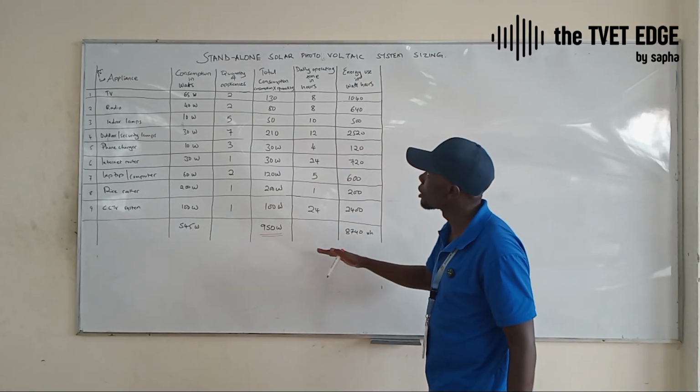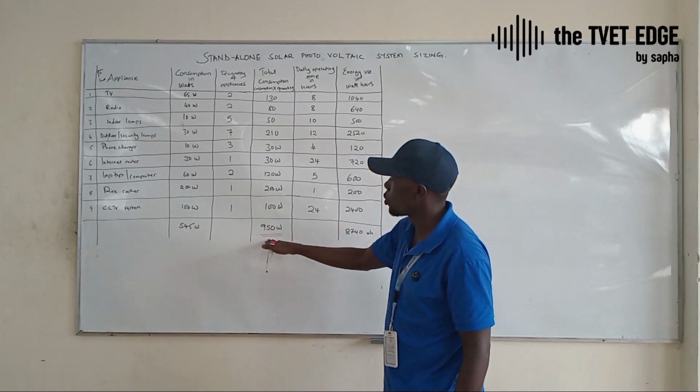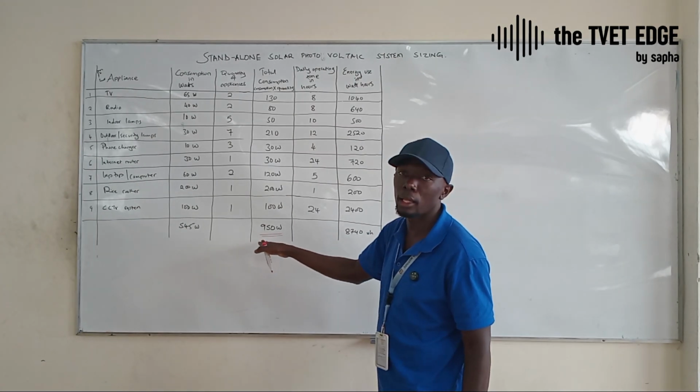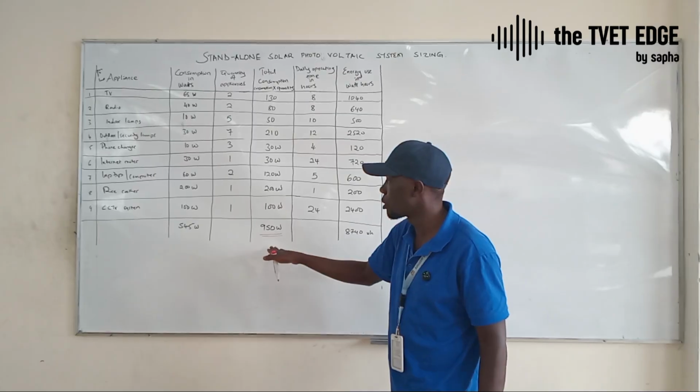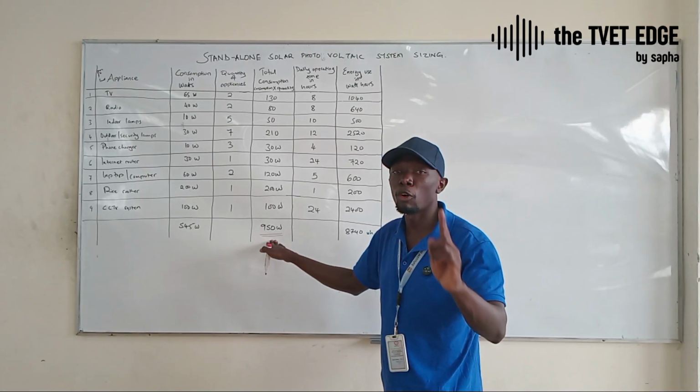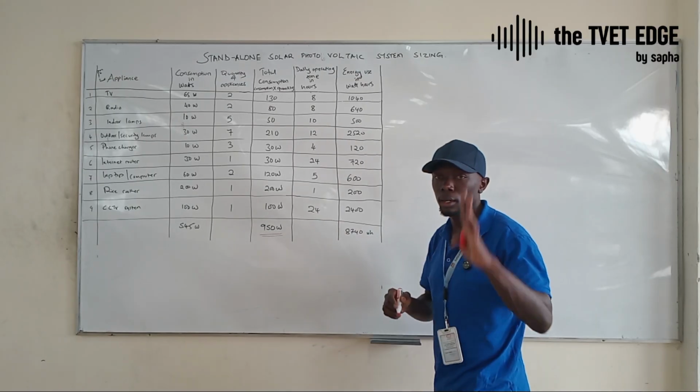So we've determined that we need to supply 950 watts at any particular point, or at some point in the life of this system, we will need to supply 950 watts. So this will guide the size of our inverter. So calculation number 1, inverter sizing.